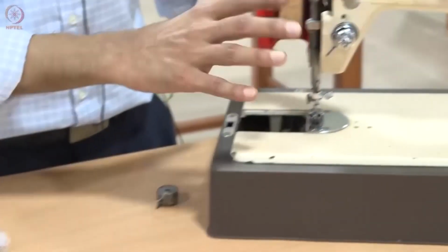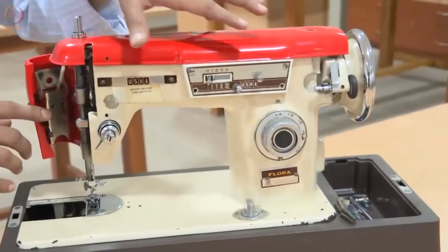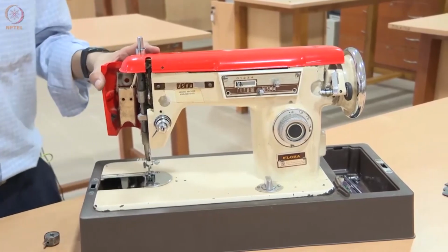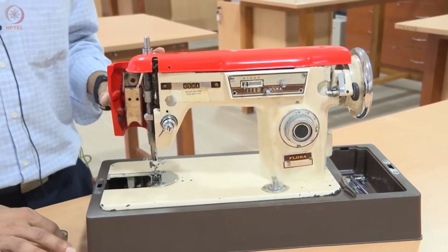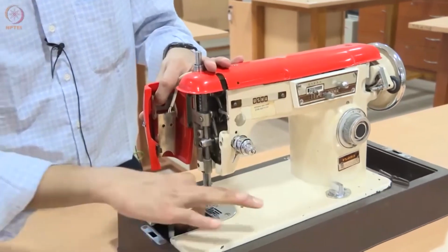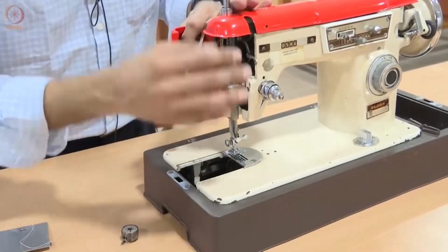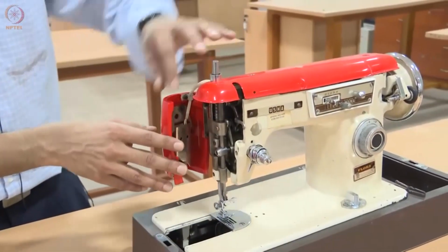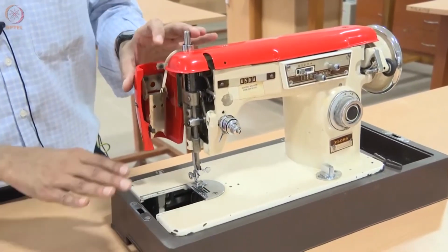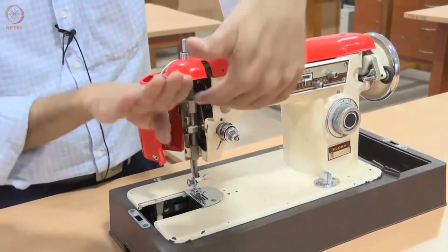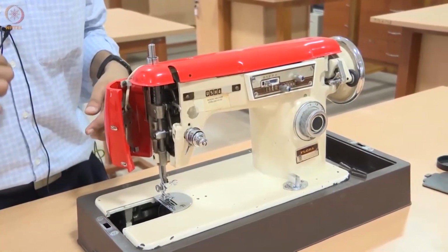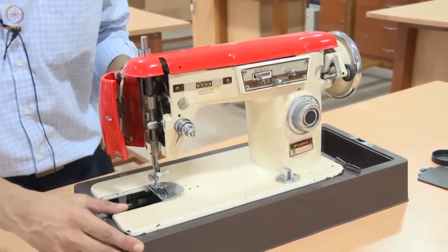If you look at a modern sewing machine, even though I call it modern, this machine is about 25-30 years old. This machine uses what is called a lock stitch. In a lock stitch, we basically need two spools. One is this, which is placed at the bottom of the machine. Another one is at the top of the machine. Unfortunately, this is missing that. So imagine another bobbin here at the top, another spool at the bottom. So we have two threads that interleave, like two sine waves crossing each other. That's how the stitches that you find in shirts and other clothing are made today.